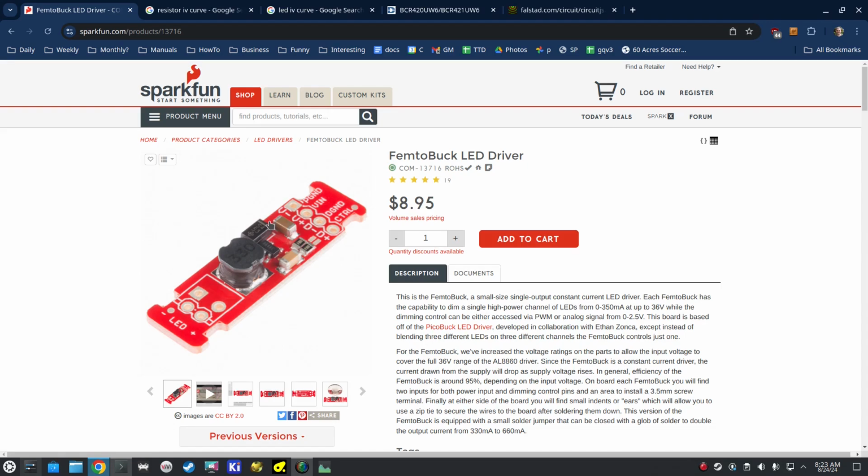So basically this thing's going to be making radio waves as it runs, and those radio waves can interfere with other things on the airplane. The most concerning, of course, being your receiver. It might reduce the range of your flight, or it might cause dropouts, things like that. I'm not saying it's going to, I'm just saying by the very nature of it, those are the kind of problems that can come up. So if I was to use one of these, I would either go with a plane that I can stomach losing, or I would do a lot of testing.